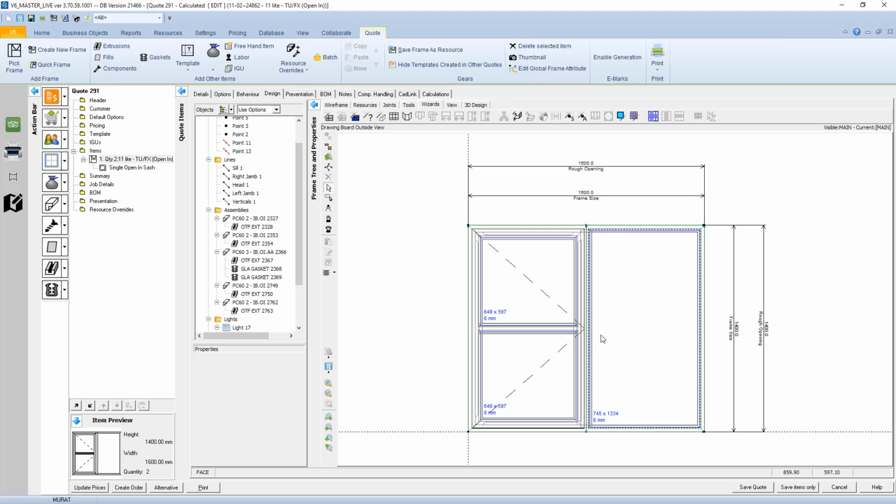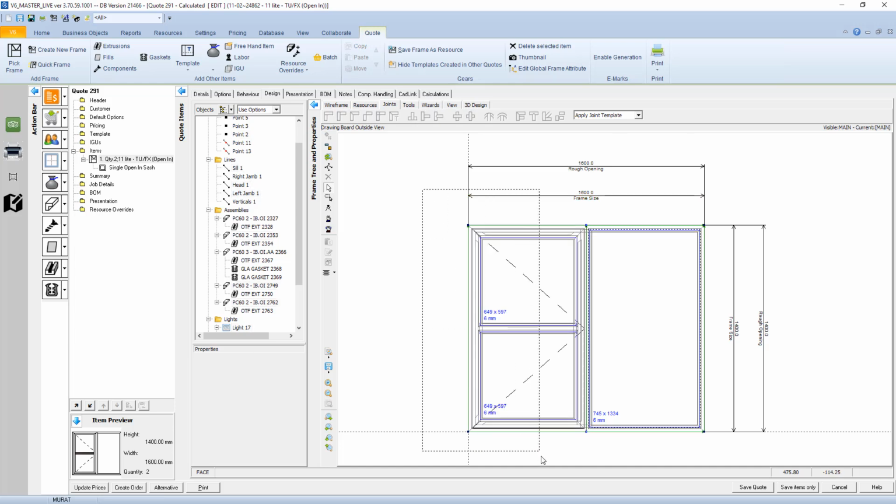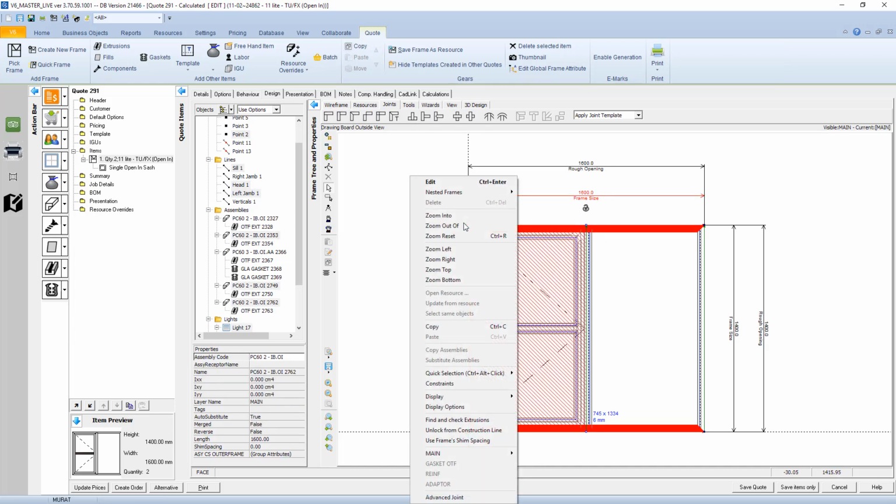And also maybe some intermediate joints are still horizontal run-through. So right now, if you want to change joints, the common ones, you need to select them manually and decide which joint type you want. And this is applicable to all layers. If you don't want that, you need to right click, go to that layer and change the joint type, one by one.